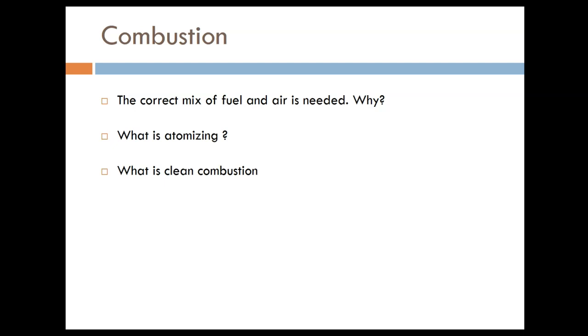So we need the correct amount of fuel because we need to burn the fuel completely. We don't want any unburned fuel, and you don't want to have excess gas as well. The right amount of air is very important. So keep that in mind, and usually you adjust the air last, and it's the final touch when it comes to complete and correct combustion.